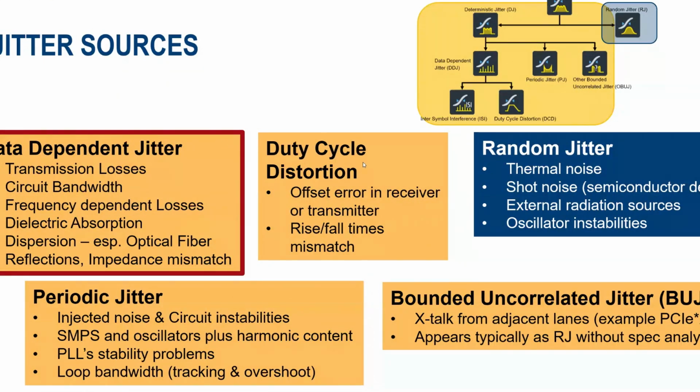So in measuring jitter, if we think about it as random, it's a pretty easy approximation. We can just say, hey, it's Gaussian, measure the standard deviation, and then whatever observation time I want, I can just use that number of standard deviations. And observation time is typically specified in terms of bit error rate, which is another way of saying, how rare is it for a timing transition to happen at a certain distance from its nominal location. And again, you want that distance to be less than half a bit interval or a unit interval so that you would not have any bit errors in that observation time. That's really why we talk about jitter in terms of bit error rate, because it's really an observation time that we're talking about.